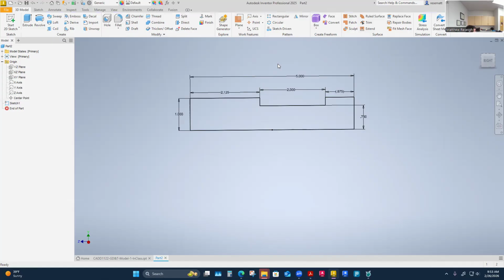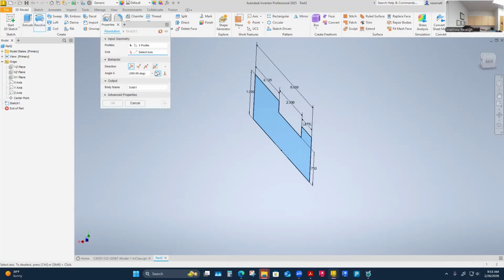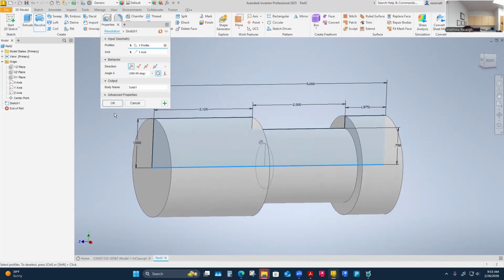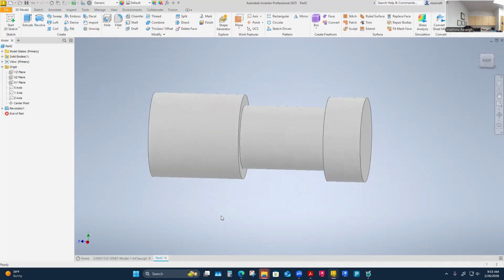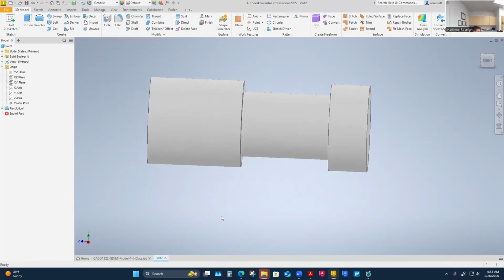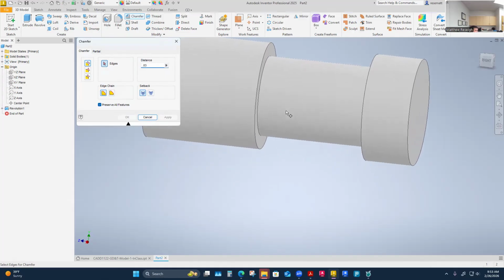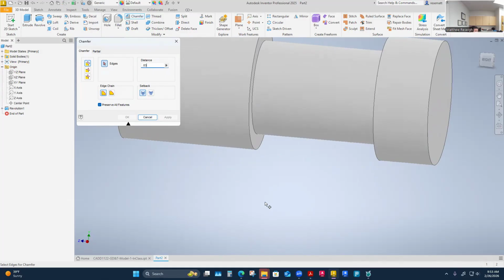This is a finished profile, so with my finished sketch, revolve that around this axis, which is the Z axis. That looks correct. It does have some chamfers on it, so I'll go ahead and put those in. Each hard edge here, there's 4 edges, has a 0.03 chamfer by 45, so it's a symmetrical chamfer, 0.03 by 0.03. So we'll do a chamfer there. I just need the distance to be pretty small, 0.03. That's about a 32nd chamfer.